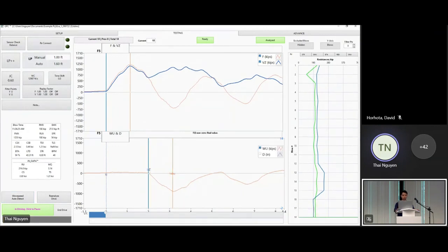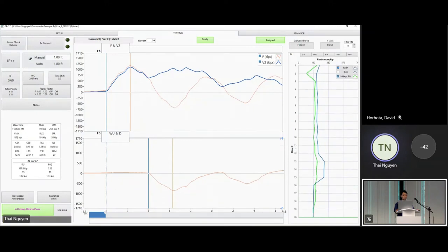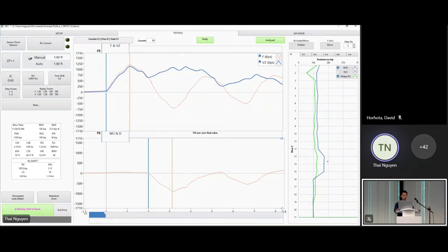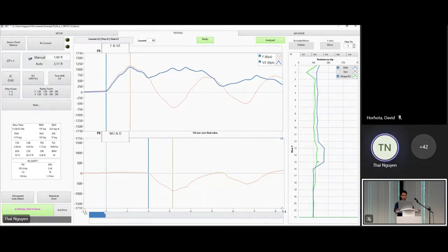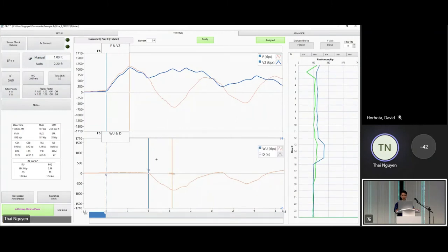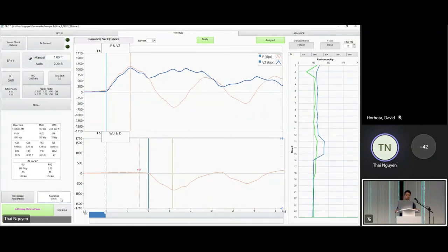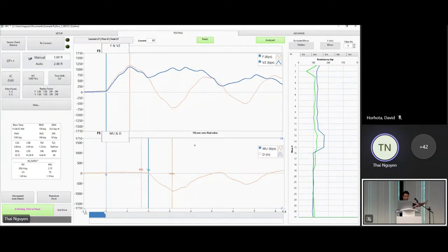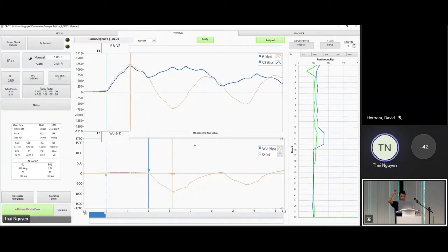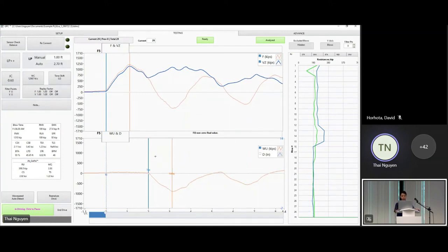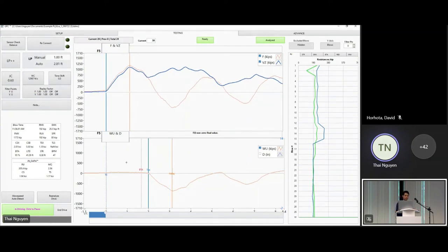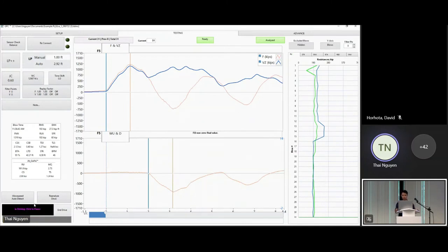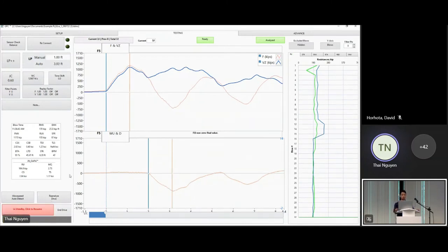It automatically picks the right wave speed for you. It has not updated the graph from blow 1 to 15 though. If you want to update from 1 to 15, you need to click on reanalyze drive. The priority for the program now is going forward, going for the next blow, not the existing blows. So you would want to do that when you have standby time, downtime. For example, right now the hammer has a pause. Now you have downtime, and you click that, it will reanalyze the whole drive.